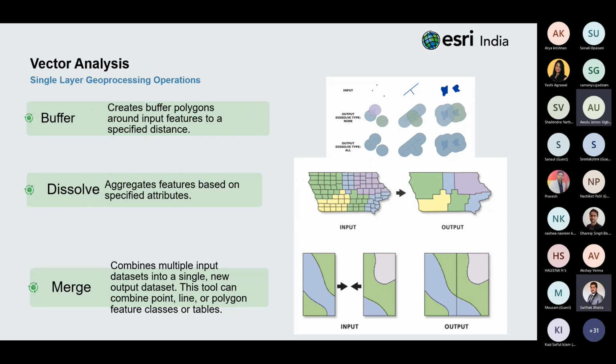ArcGIS is actually excellent for querying your database based on spatial relationships defined in the software, for instance, on the basis of proximity, containment, and intersection. In essence, spatial querying is similar to finding features that are located in a certain way relative to other features. So as we were talking about earlier, querying objects within the same layers or between different layers with different geography is possible, and that actually helps us analyze the vector data properly.